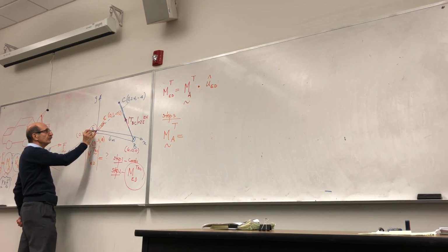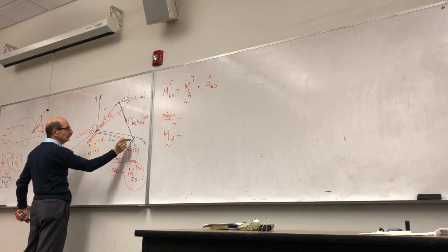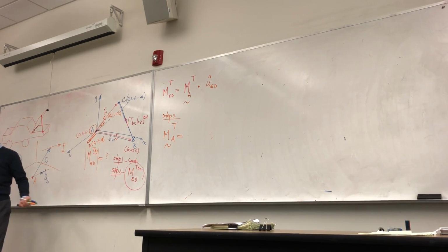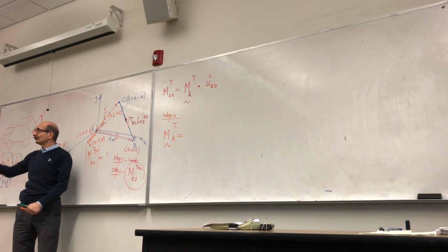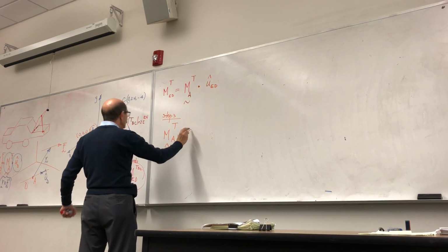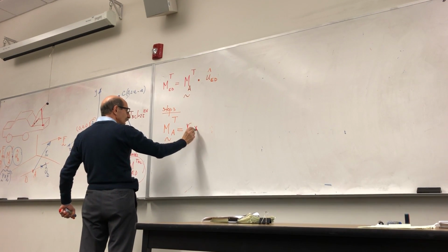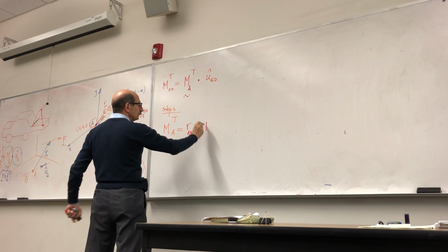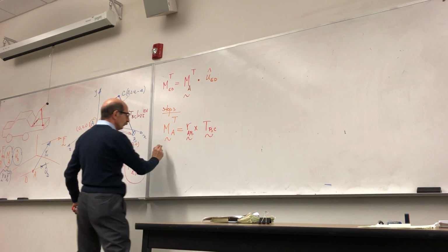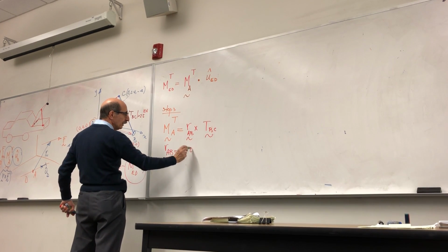Because you have this choice: either this position vector or this position vector, right? Which one is again the easiest? This, because that has only one component. So I choose R being AB, okay, cross that force BC. So R of AB, the equation for that is simply 6I.